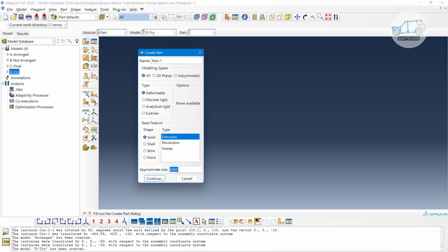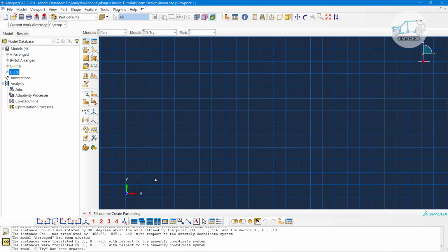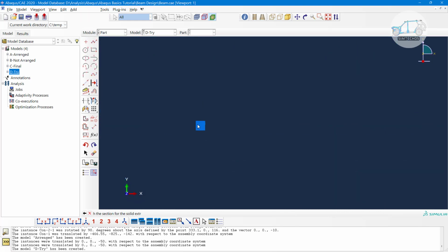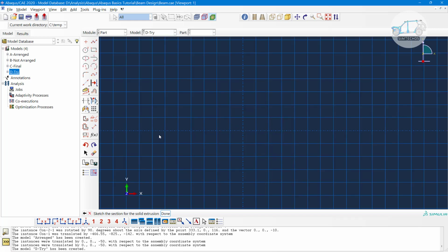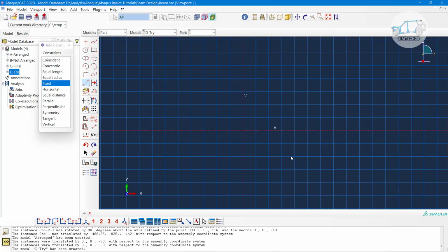This canvas size is important, as I also mentioned in my previous videos. This is the size of the sketch canvas, and that is the canvas actually. So always start with the reference axes. Just go to define the first 0 point, and then the second point, again first 0 0, and then the second point is somewhere in the vertical, and make them fixed. So your assembly will not move.